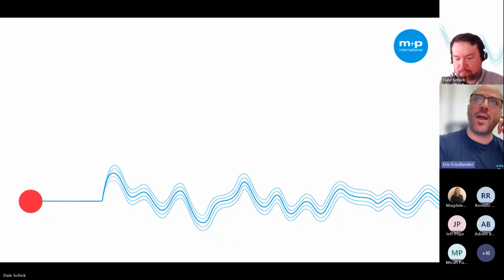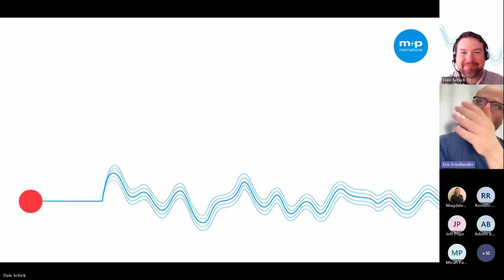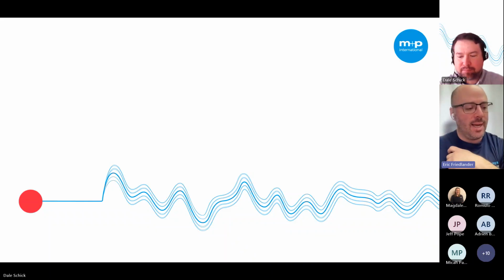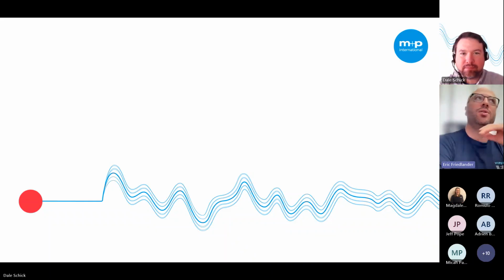It's not a sine wave, right? But if you over average, it's easy to obfuscate issues, especially at the beginnings and tail ends of tests where you might not have had enough control loops to make drive adjustments yet. And especially at the end, if your system is screaming across the finish line and hitting limiters, then you might see it struggling towards the end of the test, and some averages might obfuscate that. So it's good to have a balance of both.